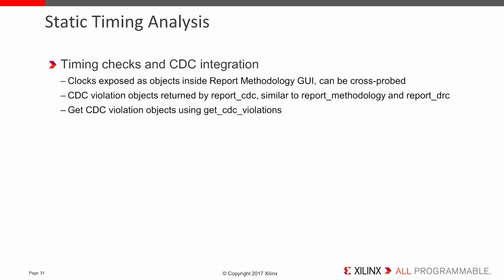For SDA, just a couple of enhancements. Clocks are now exposed as objects inside report methodology GUI, and they can be cross-probed. Report CDC now returns CDC violation objects similar to report methodology and report DRC.